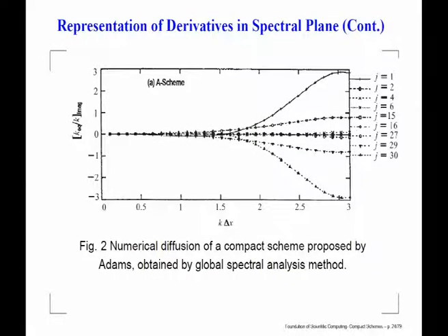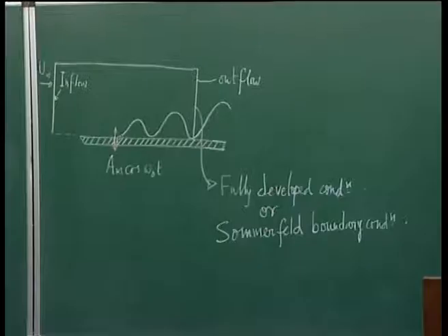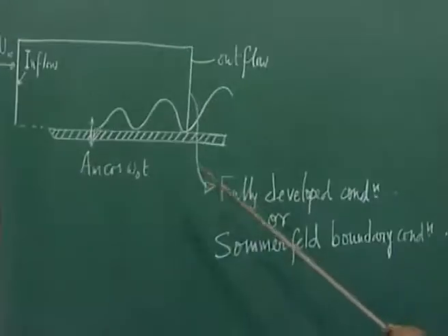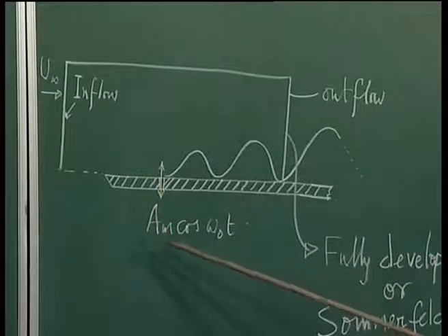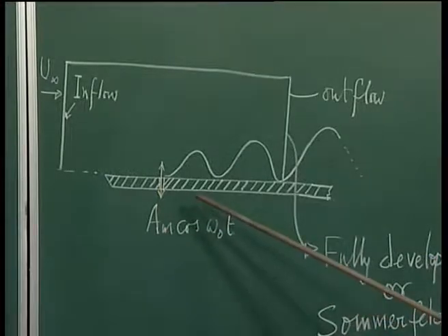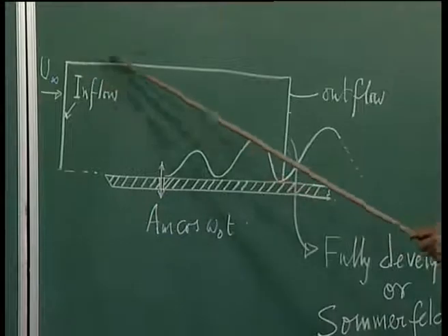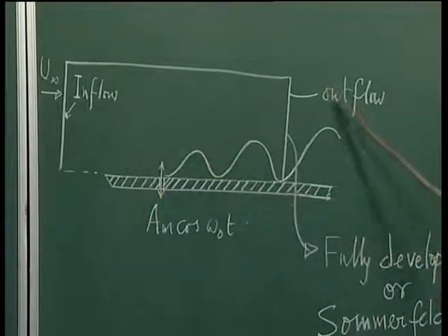Here we have talked about the dissipative property of the Adam scheme, and what we notice is that it becomes more dissipative as you move towards the outer part of the domain. And interestingly enough, this could be very beneficially used in practical computing, and let us see how it is done through an example. What we are seeing here is called a receptivity of a flow over a flat plate. What essentially one does here is excite the flow at a fixed amplitude and a fixed frequency, and the flow is computed in the domain guided by this inflow as well as the outflow here.